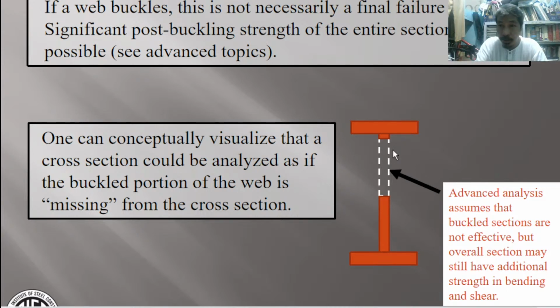As the concept suggests, there's no buckling on the tension side. So only on the compression side, there is a hole. But if you are using a perforated type of web, the material doesn't have any meaning whether you are in tension or compression. It is according to the perforation design. Okay.